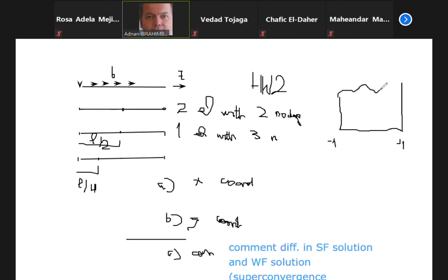So this here would be the true function. This is this integral from -1 to +1. It could be internal force vector, it could be external force vector, it could be a stiffness matrix component, and so on and so forth. So what I do is basically I take a replacing polynomial. Let's say if I replace it by 2 points, I take a point here, and I take a point, let's say, there, and I make sure that I replace now the true function by some kind of approximation that matches this function only at these 2 points.